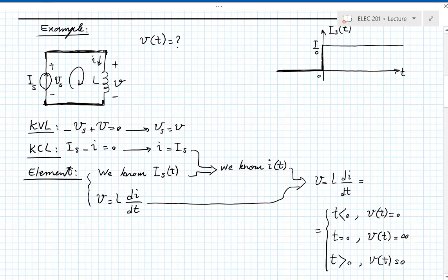If you have an inductor and you connect it to a current source and turn it on, something bad will happen. Because that sudden change in the current of the inductor requires, momentarily, but nonetheless, an infinite voltage across it. That's not good for the inductor. That's not good for the current source. And it's not good for the operator there, right?